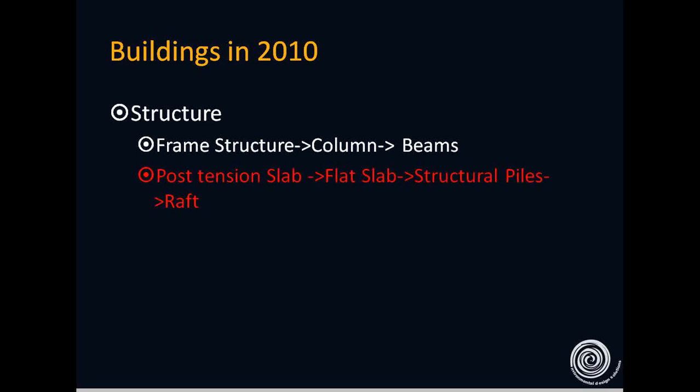There is also a major shift we have seen in HVAC from a few buildings being air conditioned to almost all buildings. A whole new range of equipments and technologies have arrived in HVAC, and each has a different requirement in terms of space and design parameters. Some of the HVAC systems added are VRV systems, earth air tunnels, geothermal cooling, desiccant systems, water cooled systems, radiant systems, and chilled beam systems.